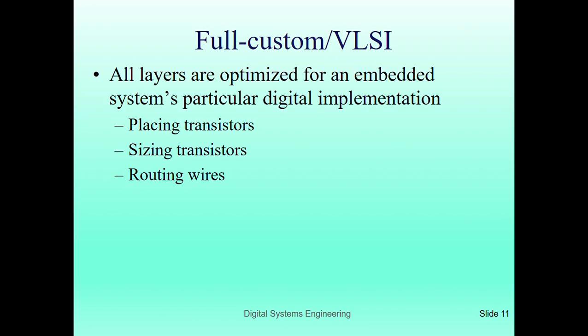The full custom design is a methodology for designing integrated circuits by specifying the layout of each individual transistor and the interconnection between them. In full custom or VLSI design, all layers are optimized for an embedded system's particular digital implementation, like placing transistors, sizing transistors, and routing wires.